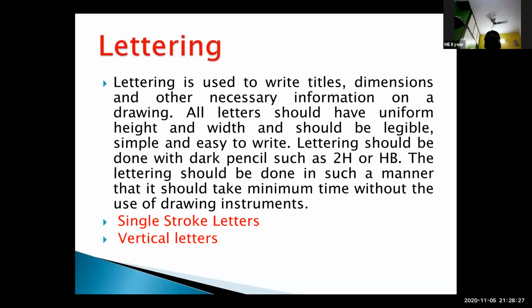Next, lettering. Lettering is used to write titles, dimensions, and other necessary information on a drawing. On the drawing sheet, lettering is important. We have to mention 30, 40 like that, and that all dimensions are in mm. We have to write the details of the front view and the top view of the object on the drawing sheet. That is called lettering.